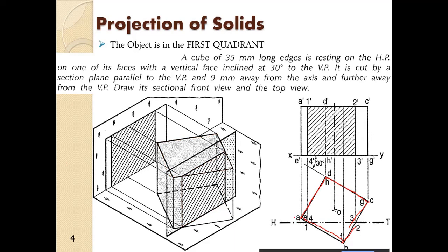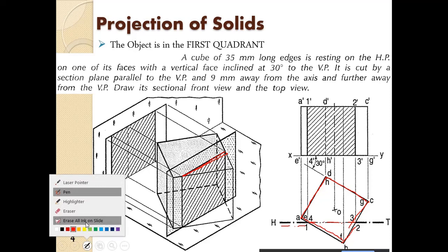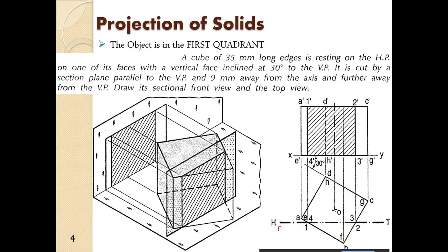Here you have to keep in mind the intersection plane has to be drawn in this manner: dash dot. And the part where the plane intersects with the solid, that part is dash dot dash, and it has to be a lighter shade than what is outside.